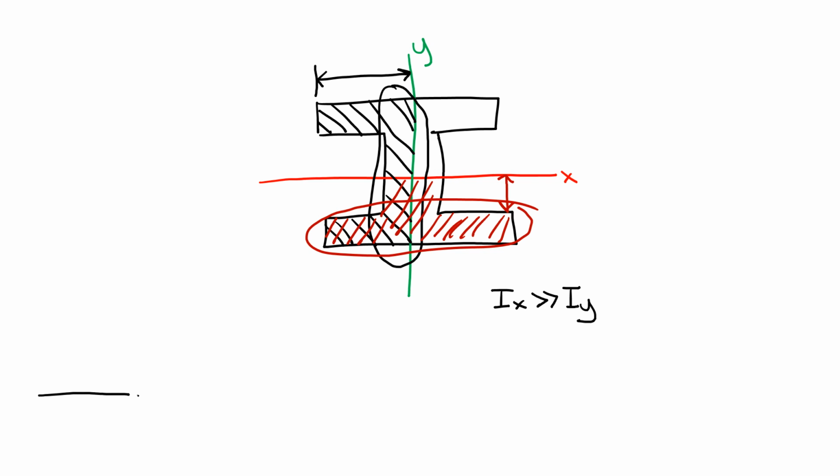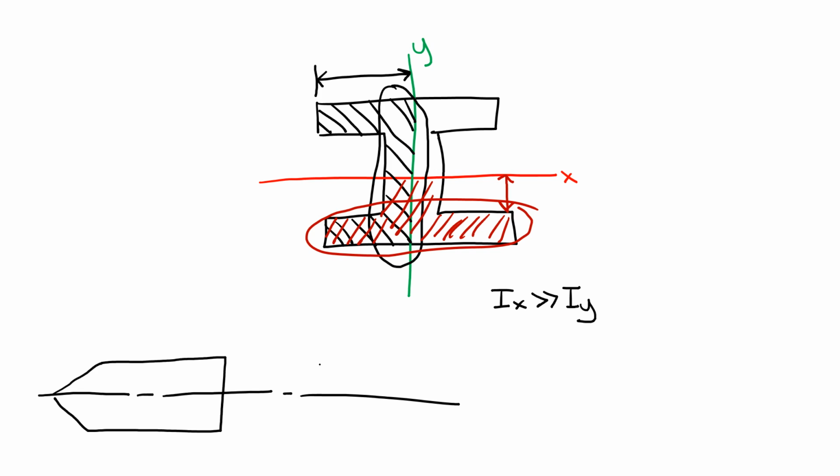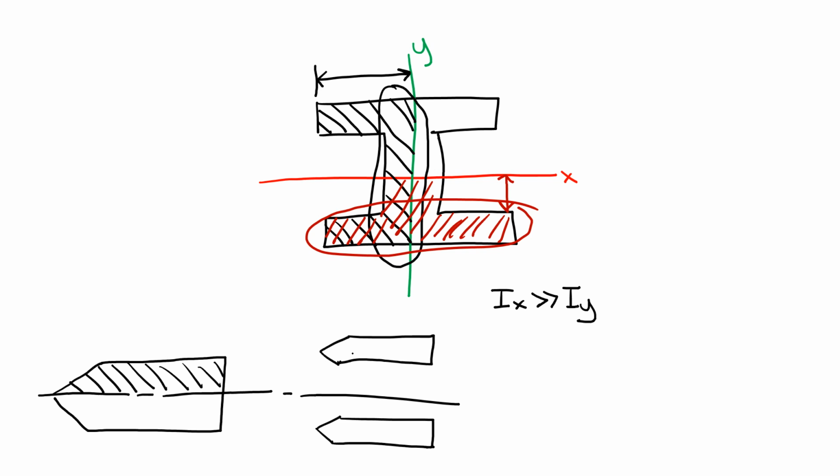So imagine that we have a center line. So imagine on this center line that we have two boats. First we're going to have a monohull, and then we're going to have a catamaran. Now let's say that the area off of the center line of the monohull is the same as the area of one side of the catamaran. This would mean that the moment of inertia of the monohull is less than the moment of inertia of the catamaran, because the distribution of area here is less of a distance away than the distribution of the area for the catamaran.